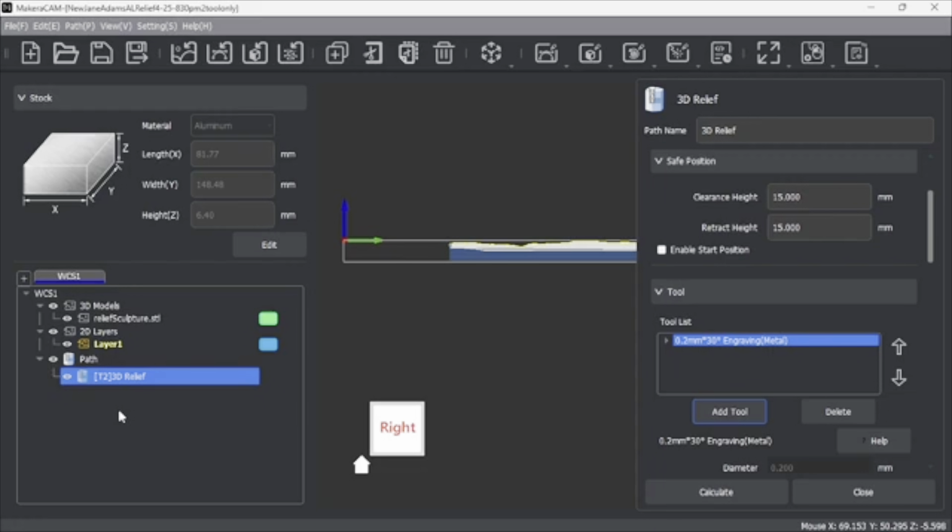And you'll see in the video where I noticed the tool collar wasn't pressed in enough, and that was from the factory, like I hadn't changed anything. So I used the tool that you would use to change the collar to press that collar in fully, and then when I restarted it, it's flushing it out just fine. So that's why you don't see both tools here.